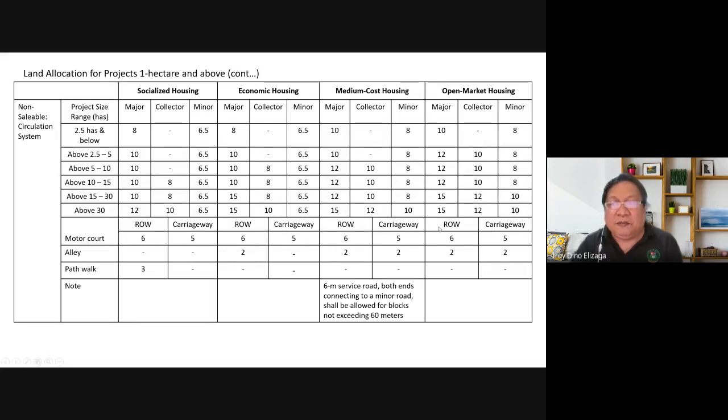But this right of way, or the road right of way, actually means the space between one property to the next, the space allotted for the road and everything else. Everything else includes the planting strip and also the sidewalk. The road proper for the car is called the carriageway, and you see that here below.